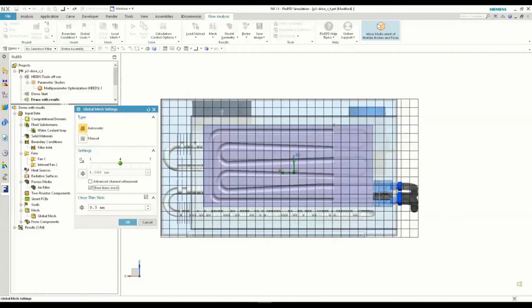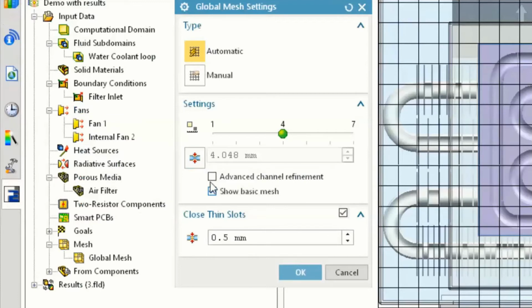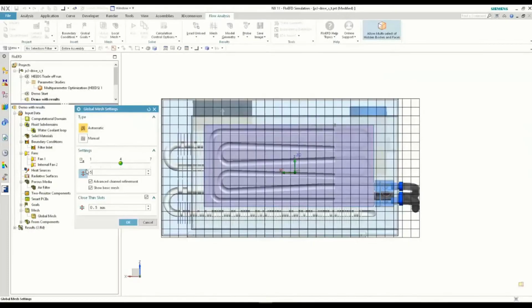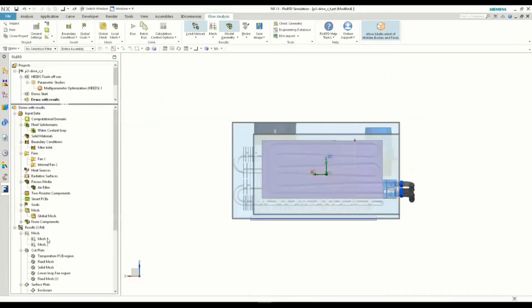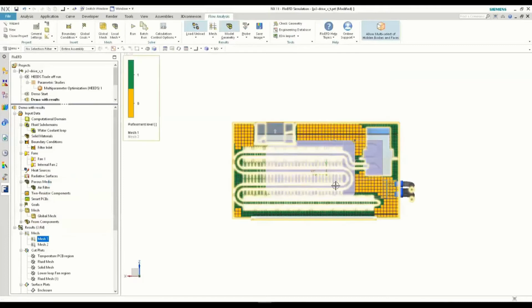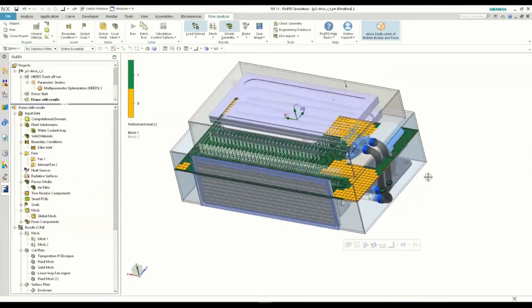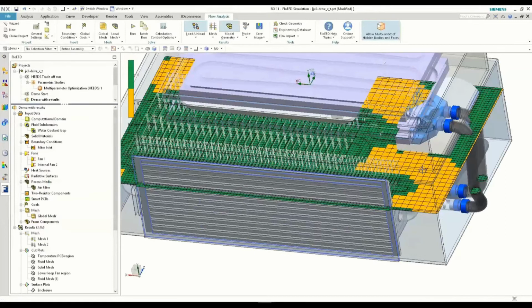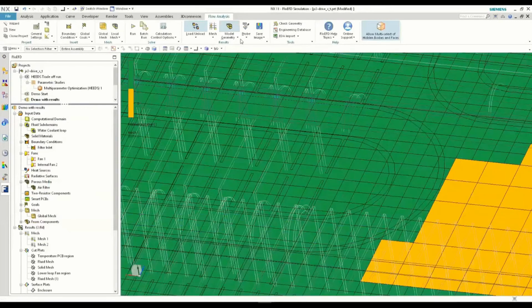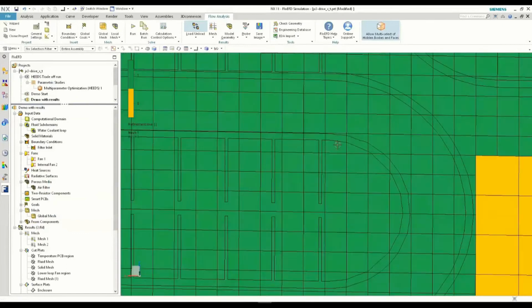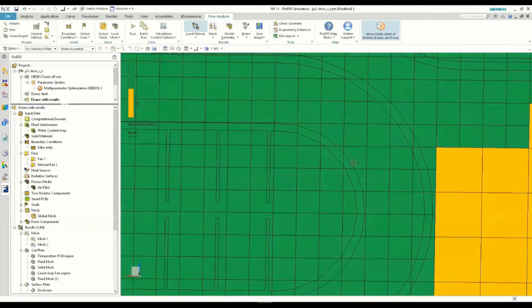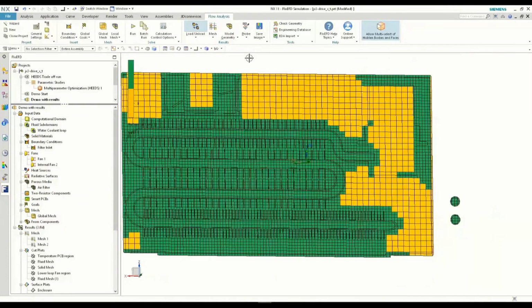And so everything winds up having this square, almost Minecraft appearance to it. But built into FlowEFD's solver are a combination of traditional Navier-Stokes equation solvers, but also empirical relationships to account for thin channels and boundary layers, so that we can get away with using a coarser mesh than maybe a traditional CFD approach.